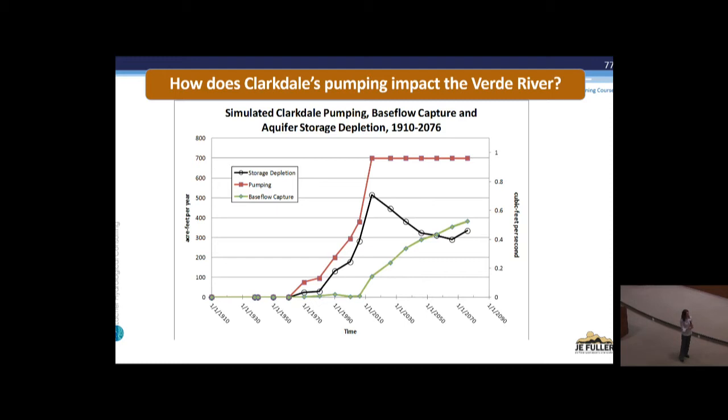However, if you look at this axis, that's a pretty small number. 0.5 CFS, it's about 0.1% of today's base flow in the river. So it is an impact. I mean, the hydrology says they're right about their intuition that they're harming the river, but it's a very small number. So if you're talking about building a recharge project, that's a lot of money. And the question is, for a small community with limited resources, what's really the best way to meet their community objectives?